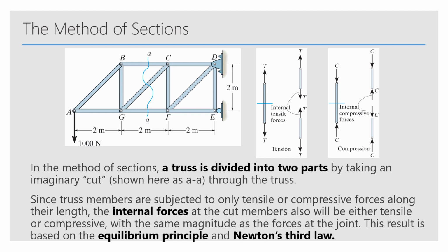If you see the right image there, if you tug on a member, the tension pulling it from the top and the bottom are equal. But if you were to split that member in half, it still would be equivalent for the amount of tension between them keeping the member together. So it's saying that it's uniform throughout, and this comes from the equilibrium principle from Newton's third law.